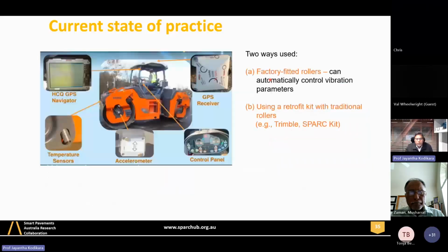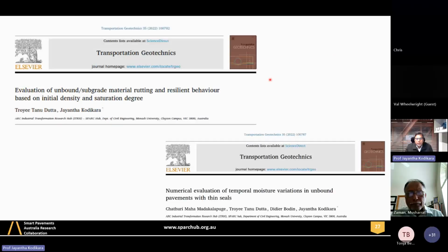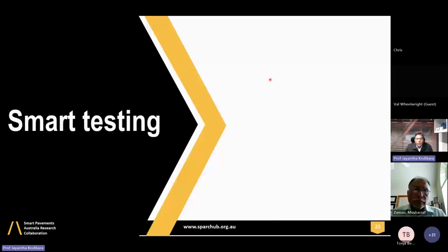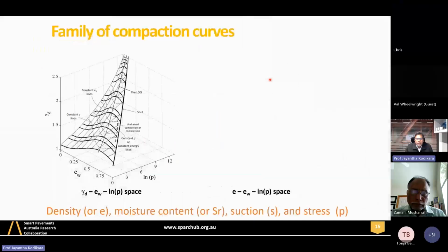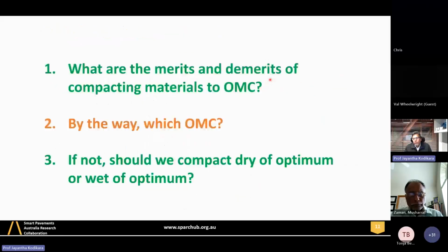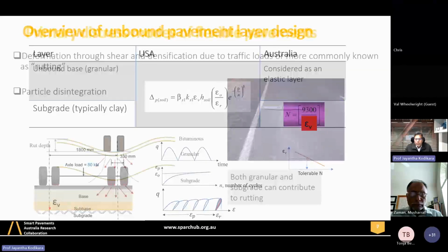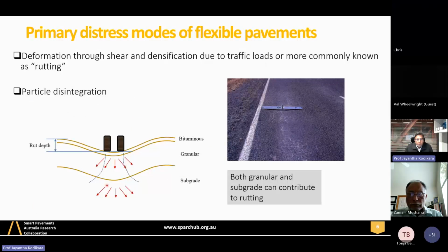Thank you very much for that question. In flexible pavements, asphalt is a relatively thin layer, and even in Australia, we sometimes ignore the structural performance of the thin layer. So fatigue cracking, as you can see here, is a consequence of rutting. Granular material doesn't crack, right? It's already cracked. Subgrade is a particulate system as well. So we don't really talk about cracking in granular and subgrade, but the bituminous layer can crack because it's undergoing significant deformation. Fatigue cracking directly is not important. If you can limit the rutting, you can also limit the visible cracking that happens on the surface.